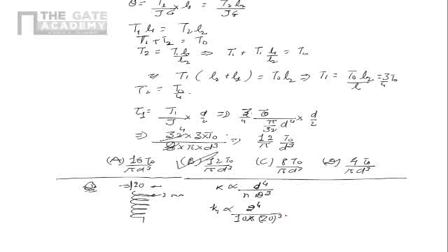So this is the original spring stiffness. Now when the diameter is changed, the mean coil diameter is reduced, but nothing else changes, so still the wire diameter is 2, so it becomes 2 to the power 4 divided by 10, and the mean coil diameter is reduced to 10.